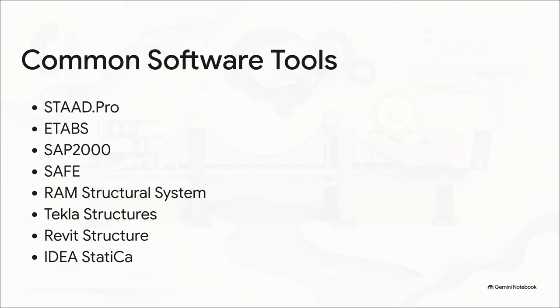So once you actually have your design criteria properly established, then and only then can you bring in the software. And look, whether you use ETABS for your modal analysis, SAP 2000 for something complex, or SAFE for your foundations, you have to remember one absolutely crucial thing. A beautiful, colorful, spinning 3D model does not automatically mean a structure is intelligently designed. The software simply calculates whatever you tell it to calculate.